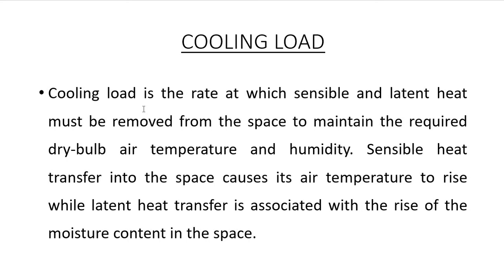So how are we removing moisture? First we convert the water vapor into liquid form, and we remove that liquid water. For converting water vapor into liquid, we have to absorb energy. So cooling load is the rate at which sensible and latent heat must be removed from the space to maintain the required dry bulb temperature and humidity.